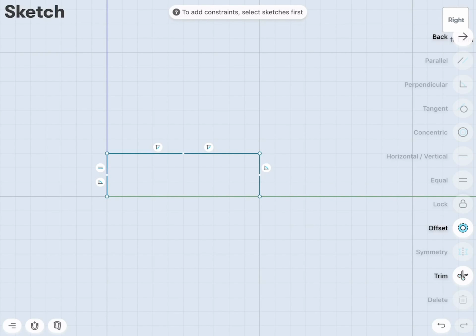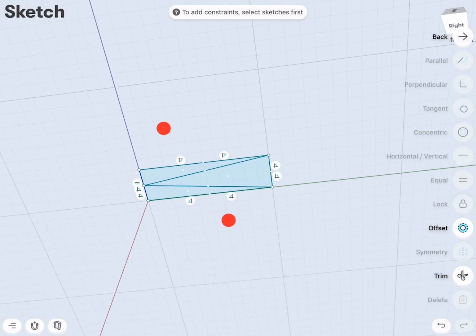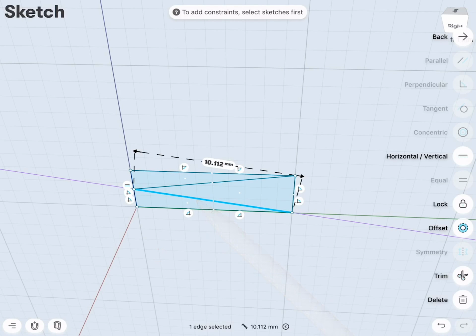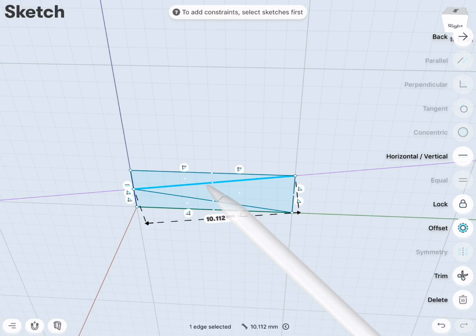The way that we're going to do that is by really quickly drawing a rectangle that's 3mm by 10mm, and we're going to angle the top and the bottom of the tooth, or rather the peak of the tooth and the valley of the tooth, by using this rectangle here. So we're going to draw these two lines, and this is the basis of the tooth that we plan on making. At this point, we're going to leave this line where it is, and we're going to rotate this top line out of plane so that it is essentially the peak of the two teeth on either side of the valley.